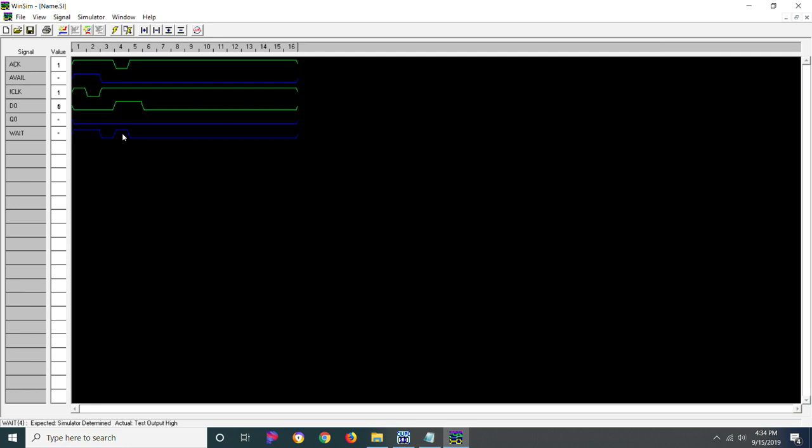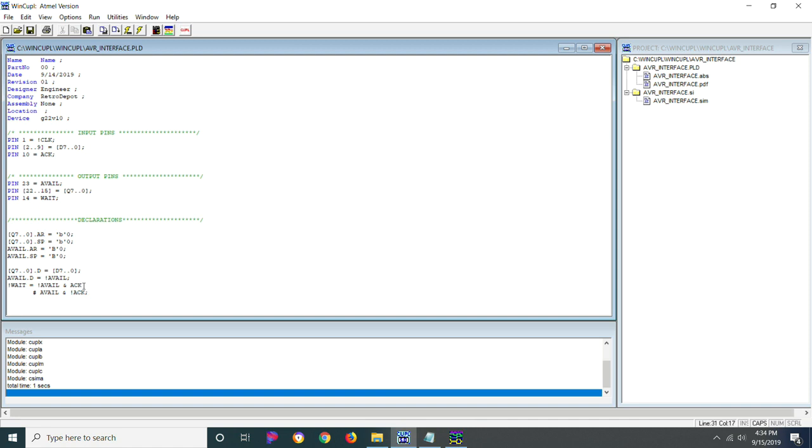what this does is it's basically a way of using the feedback from these registers in order to do combinational logic. So the best way that I can describe it to you is you're just feeding it back into the AND OR array, and you're able to use it, the output, to determine states.